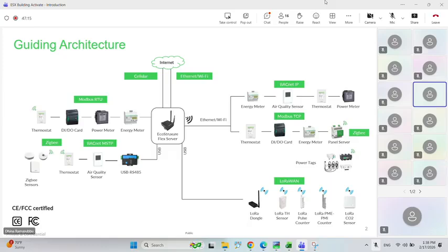The Flux will support direct BACnet MSTP or Modbus RTU; it has an onboard port. Additionally, it has two USB ports, which we can use with converters like USB to LoRa to capture the LoRa sensor data, and USB to RS485. These can be selected by the project commissioning engineer during the commissioning phase. So these are all the limitations for one Flux server. Through one Flux server, what are the things we can achieve in one site?